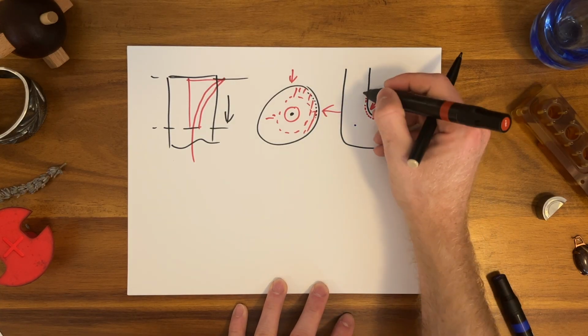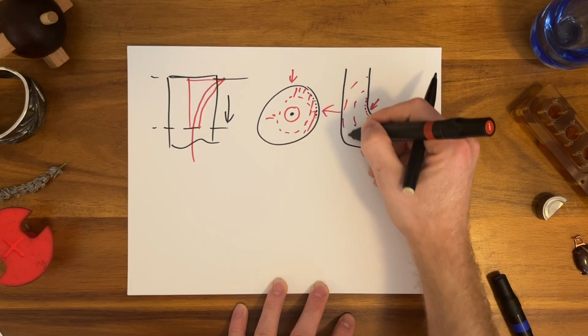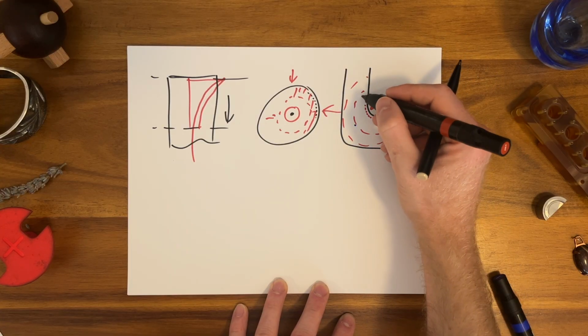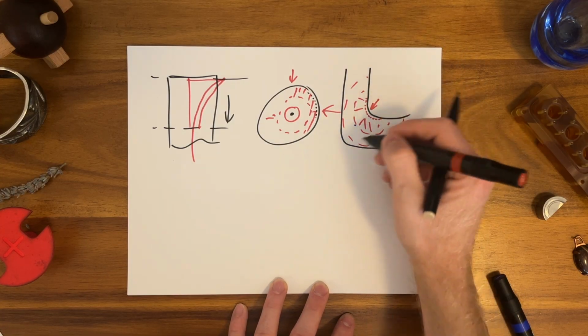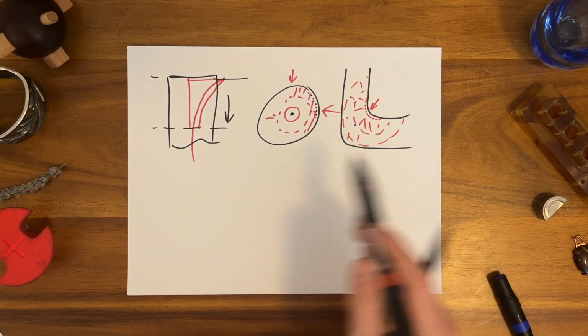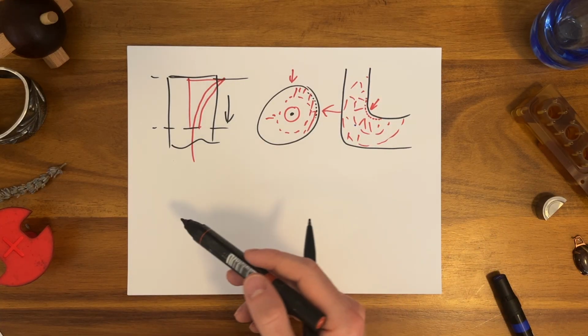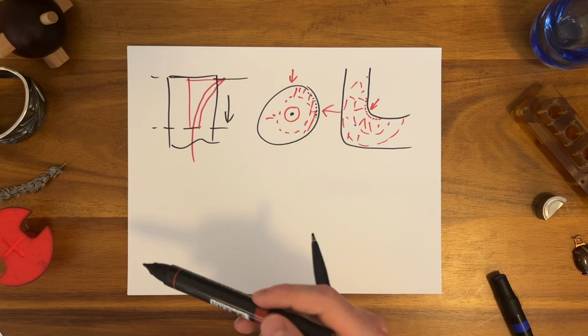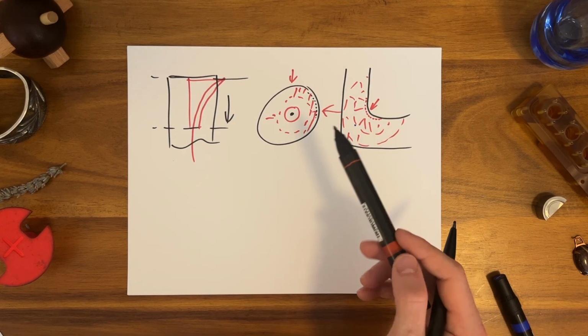But eventually, as you heat more and more, as the Fourier number gets smaller, the area keeps getting bigger and bigger. Actually, it takes more and more power to do that. So the semi-infinite solid model will actually overpredict the temperature because of this curvature.